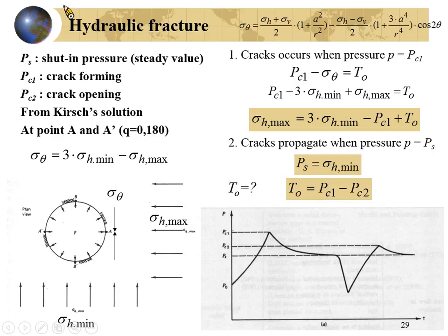Okay, for this kind of problem, like you have a balloon and you try to increase the pressure, and finally the balloon will blow up. So you increase the inner pressure. How about this? This is like a can, and you try to squeeze the can, and the can will be damaged. So you can imagine, if you have this, you should have a very high sigma theta around here.